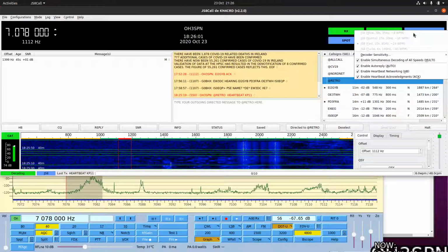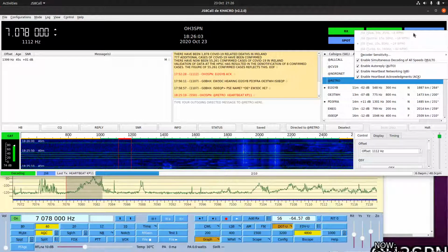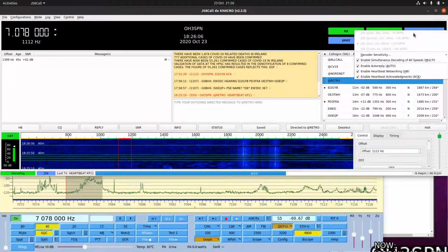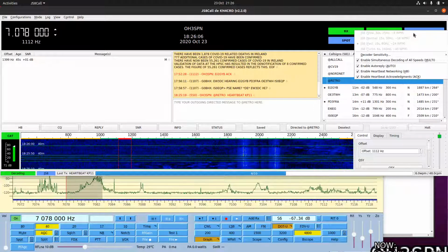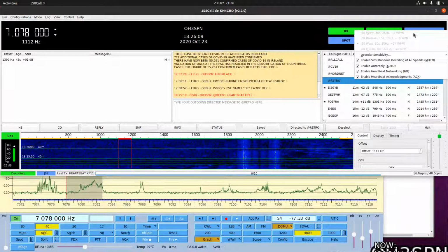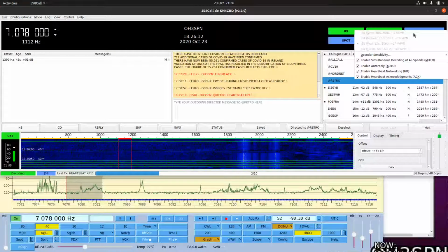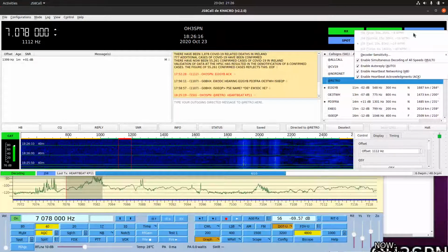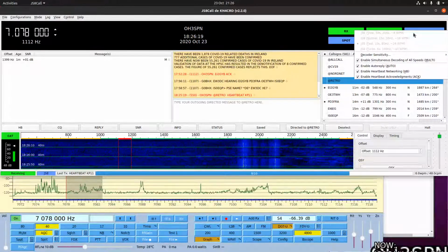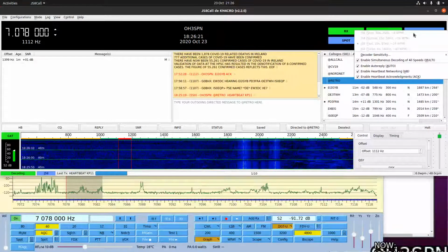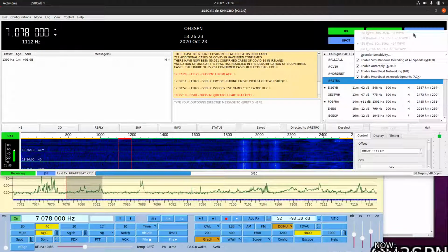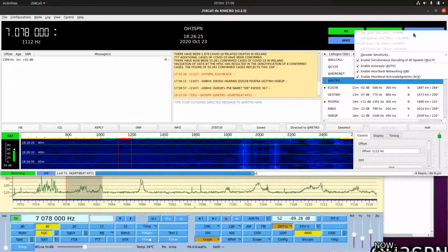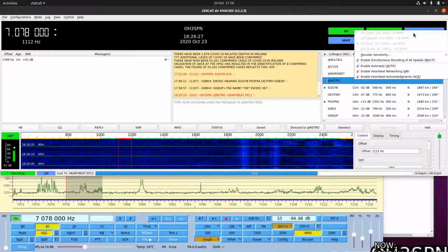I was using the built-in USB sound card interface for JS8Call, and I noticed similar problems to other traditional radios, where if you're transmitting in the middle of the audio passband, you get full power out. If you're injecting a lower or higher frequency audio, your average audio power decreases because of the frequency of the tones and the position in the passband.